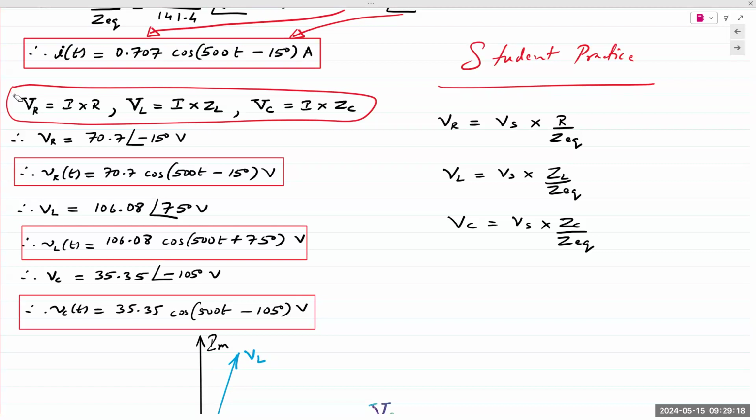Okay. So equations are based off of Ohm's law. VR, voltage for the resistor, is I times R. VZ is I times Z, voltage of the inductor, VL, is I times ZL. And voltage for the capacitor, VC, is I times ZC. As straightforward as that. So the analysis, again, is the important point I keep making. The analysis is not new. The circuit analysis is exactly the same as what we learned in chapters 1 and 2. It's the math that is different.